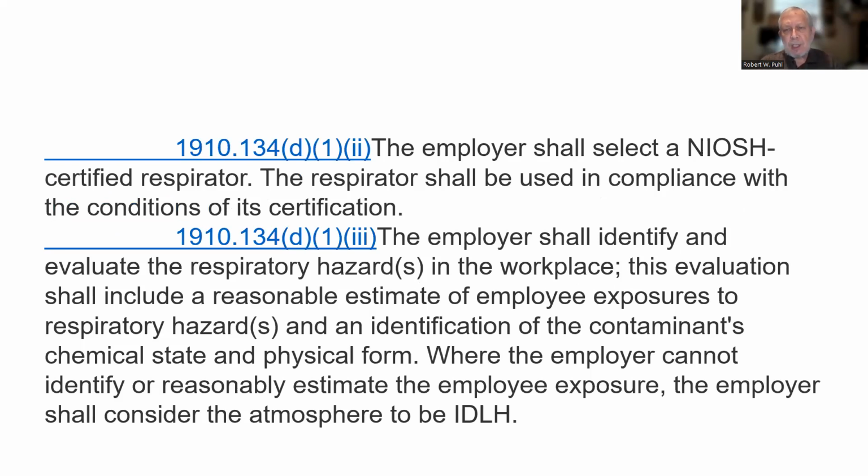The employer shall select a NIOSH certified respirator. The respirator shall be used in compliance with the conditions of its certification. Now, you notice OSHA doesn't approve everything, but NIOSH certainly does. The employer shall identify and evaluate the respiratory hazards in the workplace. This evaluation shall include a reasonable estimate of employee exposures to respiratory hazards and an identification of the contaminant's chemical state and physical form.